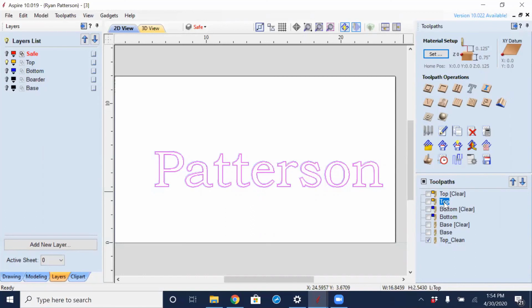There's maybe 15, 20 seconds for the tool change to happen. So having them grouped together is still going to reduce the amount of tool changes that are happening. So I would probably still keep them grouped together based on the tools, although we would have to save them in one file for a tool changer.